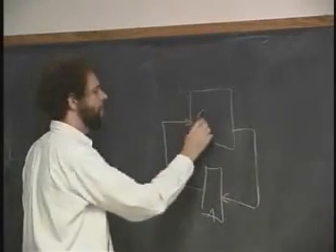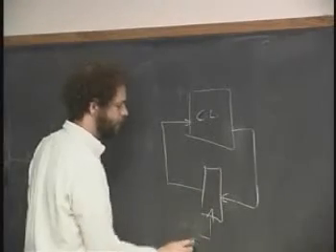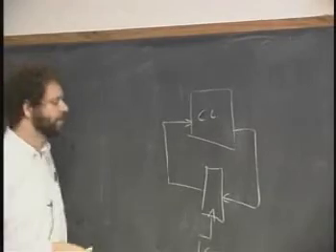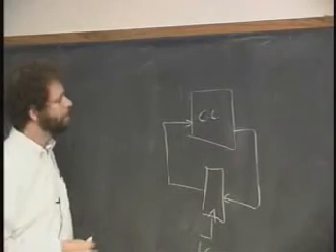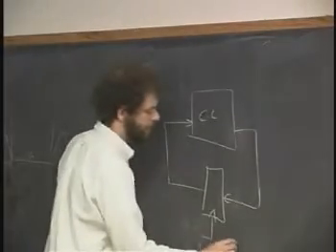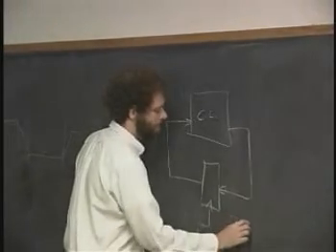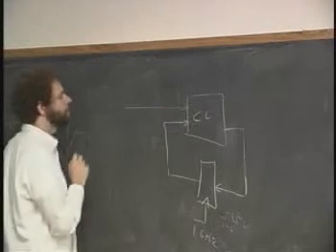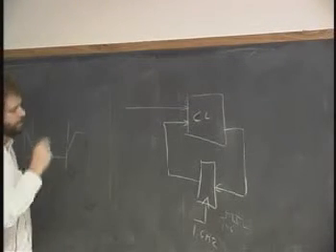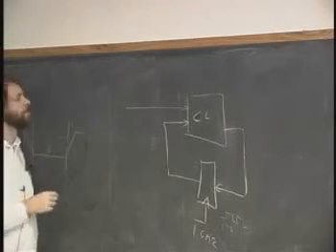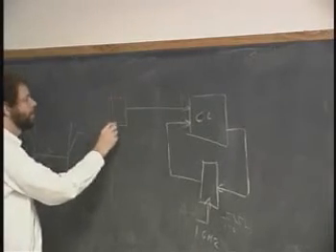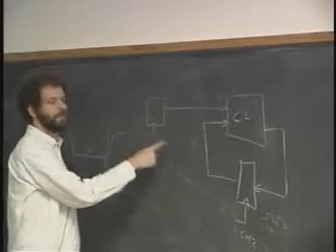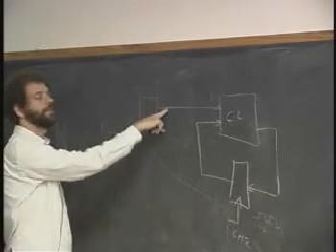Here's your FSM, combination of logic. Let's say that we're going to clock this at 1 gigahertz. This is on the inside of the Pentium 4 or something, right? It's actually 1.5 now. Let's say 1 nanosecond in between pulses. Despite their attempts to make it not so, there are actually real-world inputs to the Pentium 4. How are we going to deal with it? I'm telling you that if there's a register here, and we clock this with the same clock as here, we have to wait 100 clock cycles before we can make use of this output.